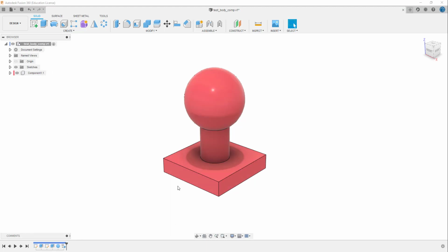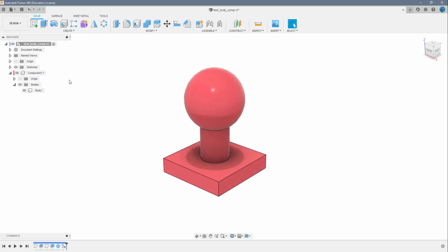But if you're halfway through modelling something, you can convert it to a component, but you just need to be aware that underneath there's no real history of how this was made. The history of this component is held under the root node, and that can cause confusion, even confusion in just explaining it to you at the moment. Okay, so let's save this here, and then we'll come back in the next video and I'll show you how we can take advantage of this now being a component to create the socket for the ball joint.